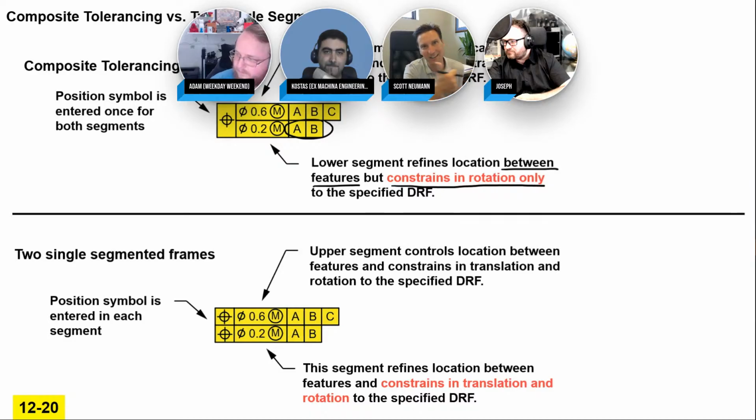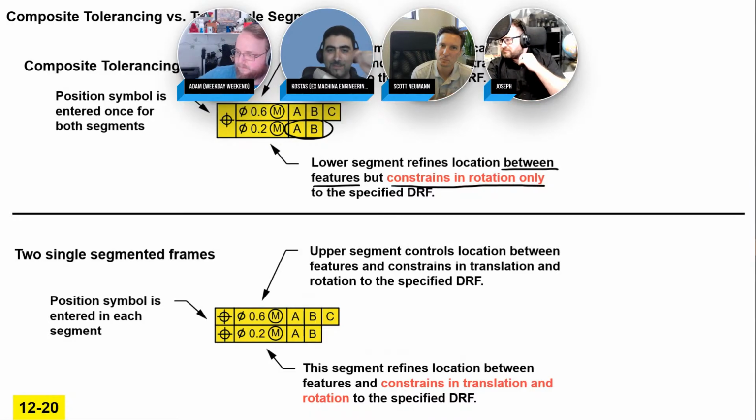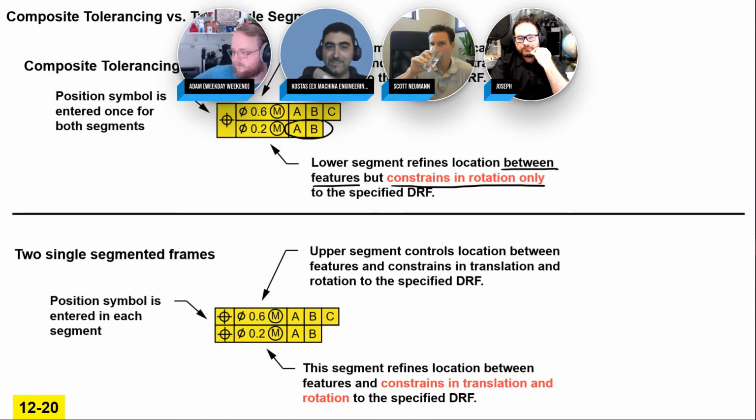And it's also different in ASME and ISO, which is why I didn't want to get into too much of the muddy water of the differences between ASME and ISO. But just to confuse everybody even further, if you look it up and understand why that happens, you will also understand why in most parametric CAD systems, you add constraints which feel natural and logical to you, and then the system tells you, I cannot do that because you just over-constrained your part. So that's the difference there, right?